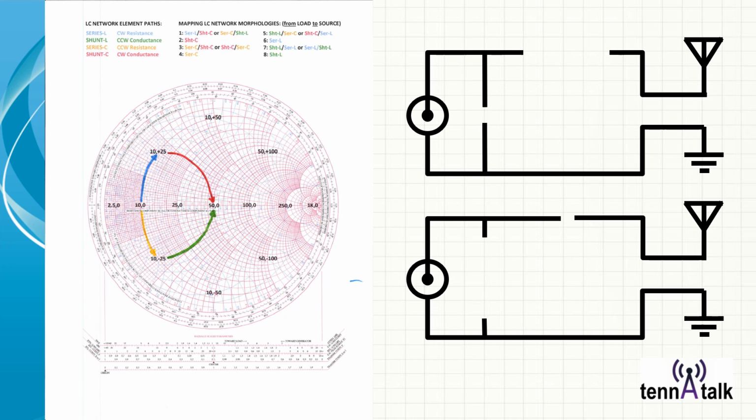So here I've got a situation where I'm starting from an impedance of 10 and 0 reactance. That's perfectly resonant, but it's a resistance of 10. That means it's a 5-to-1 SWR, because 50 divided by 10 is 5, right?